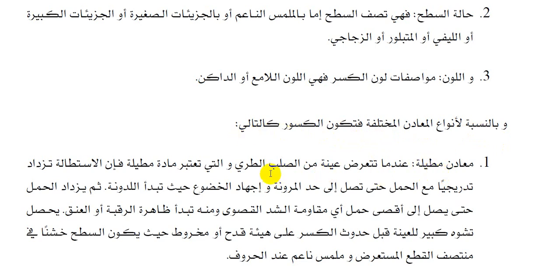When a sample of the rod is exposed to loading and is very ductile, the elongation or extension will increase gradually with the loading until reaching the elastic limit as well as the yield stress, then plasticity will be triggered. The loading will be increased gradually to the highest tensile stress, or maximum load, which is the ultimate tensile stress, then necking will be triggered as well.